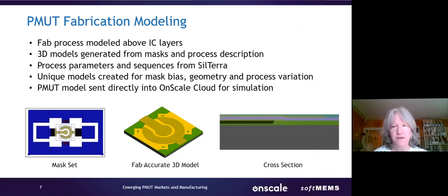And so one of the things that we do in order to create a design environment for the designers of the PMUTs, SilTerra's customers, is that we model that fabrication process. So we model the fabrication process above the IC layers. As Arjun pointed out, we have an interconnection layer, which we measure, we model, and then we model the PMUT, the cavity, and then its final interconnections. So we create these 3D models from the masks that the customer designs or from test structures from SilTerra and a description of the fabrication process that Arjun showed you.